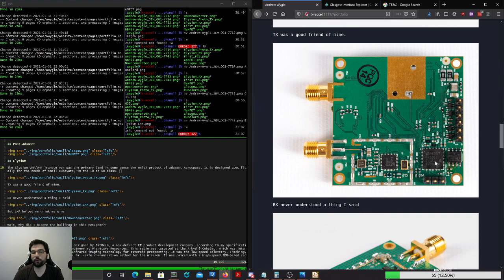Another place that you'll see it a lot is old video games that had battery-backed SRAM for save games. You can often get a drop-in replacement FRAM part, and then you don't have to worry about the battery running out. They also have great endurance, 10 to the 14th, whatever. They're very stable compared to Flash, where after a while the cell wears out. You can only have so many writes and reads. You can do like 1 times 10 to the 14th writes, I think is the number I'm trying to pull out of my head. So it lasts forever, unlike Flash, which is one of those things that almost doesn't actually work. And we just kind of gaslight the electrons into thinking that it works with lots of error correcting coding. And FRAM is not like that.